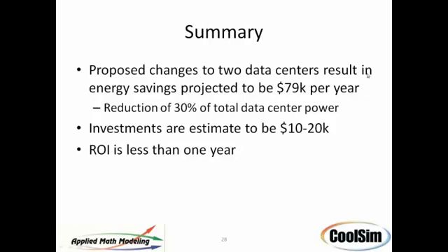Now, I have researched this pretty heavily and found that it is generally true for all heat rejection systems, whether it's chilled water or DX-based units, because they all use an evaporator, and the reason that the number is there has to do with the reduced lift associated with higher return temperatures. The higher the return temperature, the less lift is required to increase the pressure and therefore the temperature to get that heat rejected into your sink, your outside heat sink. So it has to do with lift, and all of these systems work the same.